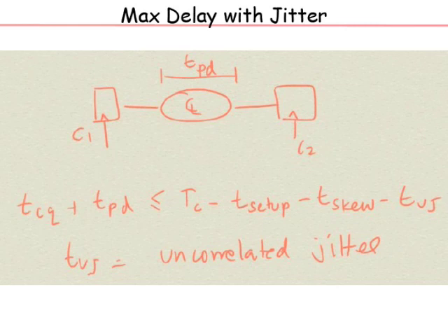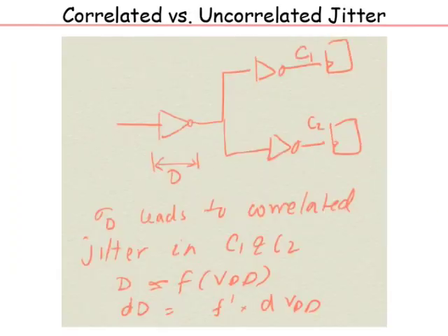That portion can be simulated, and then when it goes through a clock distribution network, as I said, the clock distribution network adds a certain jitter which is related to noise in the power supply. So it really comes down to how well you design a power supply network. If a power supply network is very noisy, it will lead to a lot of jitter and noise in the clock distribution network also. They're all tied together. But you can put a budget, you can say, my power supply shouldn't fluctuate by more than 5%. Typically a 5% change in supply leads to a 5% change in delay. Like that you can come up with ballpark estimates of what the variation in delay will be.